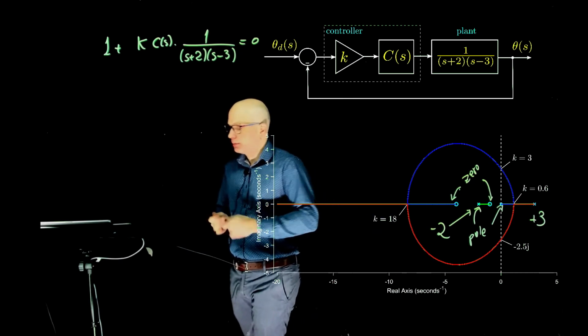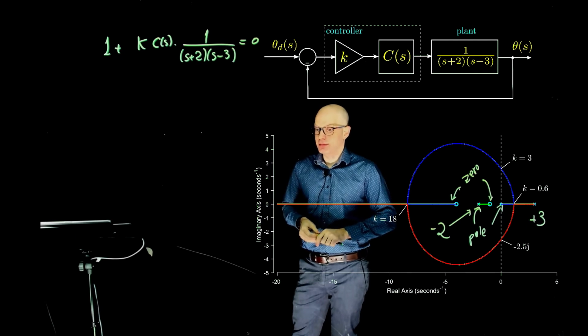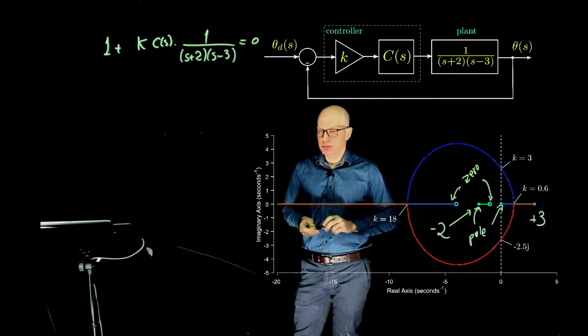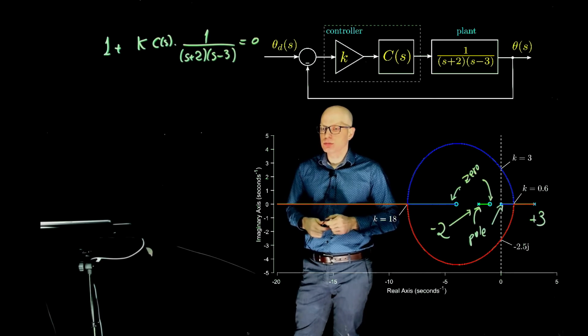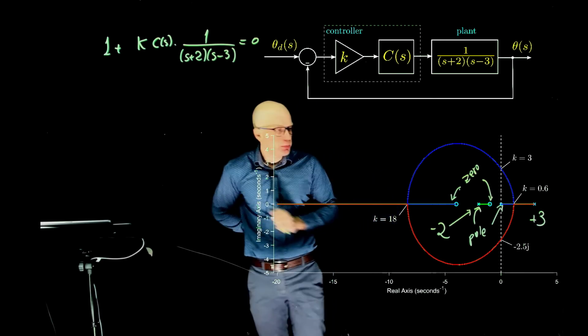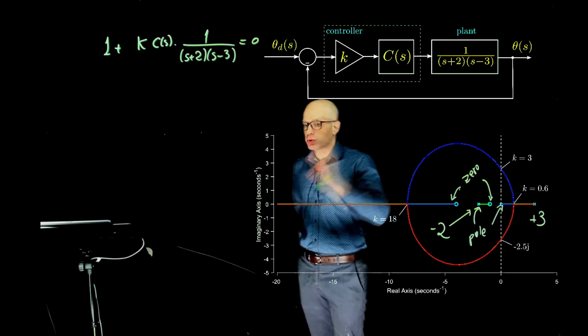PD. No, I don't know. Well, sorry, it should be a PI or PID controller, because there's one pole at zero, so there should be something added, and then there should be an integral, but I'm not sure if there is a derivative of that. Very good point. So one thing that we can say for sure is that there is an integral component somewhere,